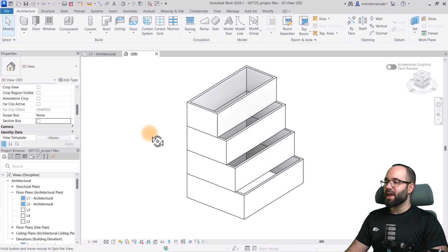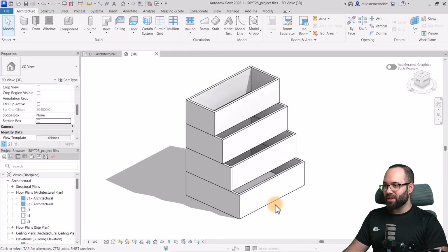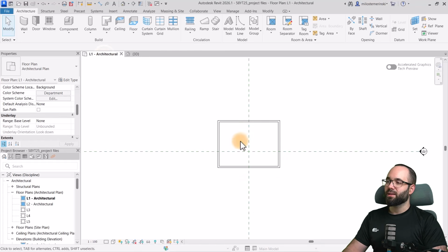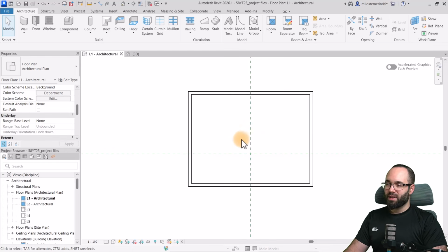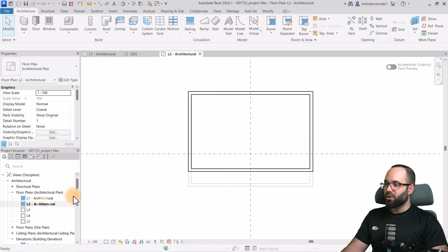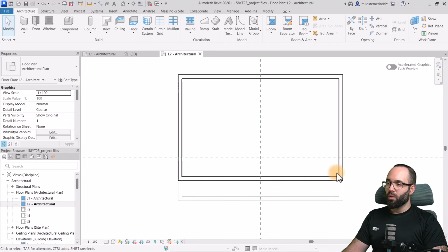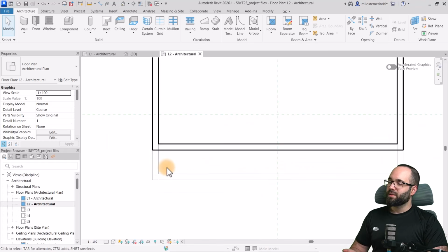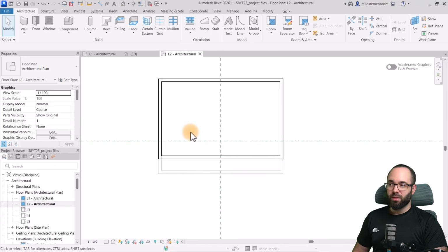And here we are in Revit, and this is the model that I'm going to be using to demonstrate this, because we can now easily differentiate which wall is on which level. So here we have 4 different levels of floors, and let's jump into the level 1 floor plan and start exploring it here. So here we have our 4 walls. Now, if we jump on to level 2, what you'll notice is we have the 4 walls, and we have the walls that are below that visible as well. Now, this is usually due to the template setup, and this is the most common template that people use, so this is why I'm using it, and this is the result you're going to see.